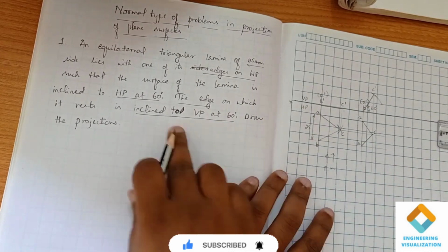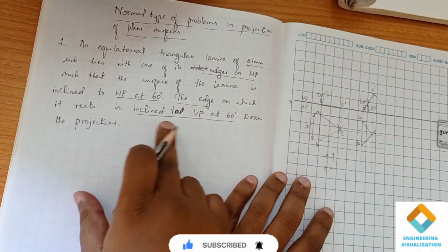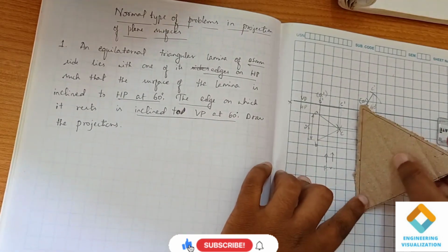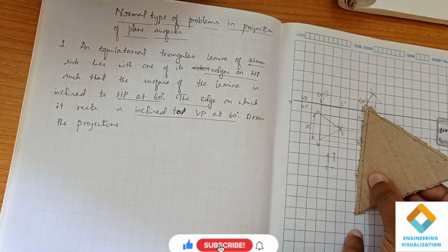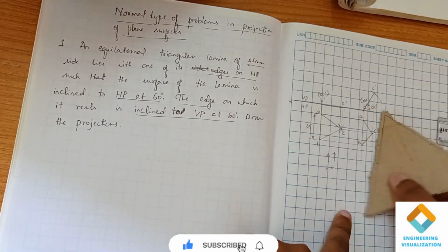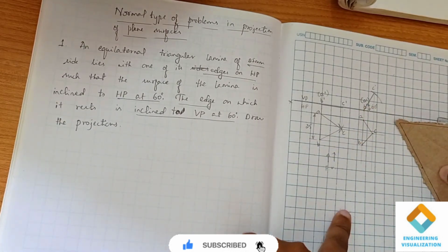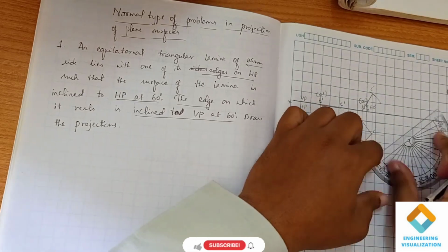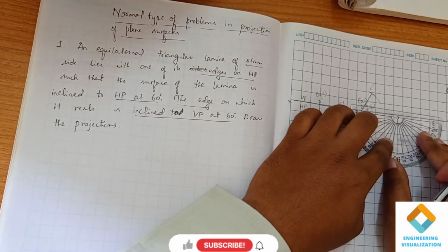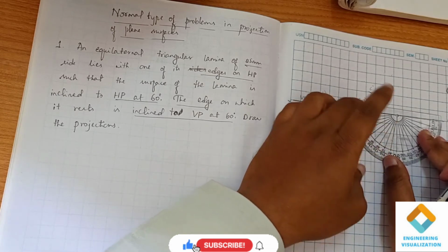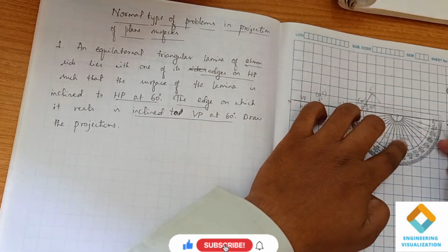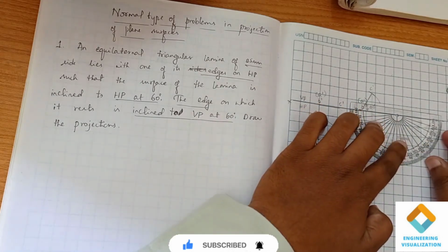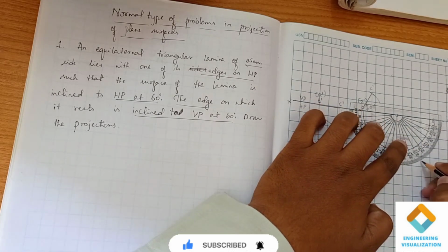Now we see the question: the edge on which it rests is inclined to VP at 60 degrees. We know that it is like this, it is inclined. Now we have to incline the same edge. What we do? We are going to incline with respect to VP like this. For inclining that, first we are going to draw an angle line here. For how much? It is 60 degrees. So we are drawing an angle line of 60 degrees.